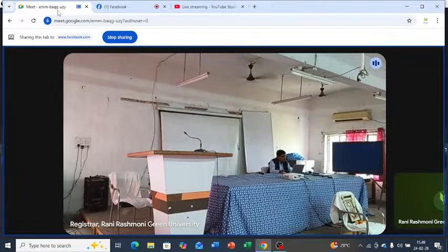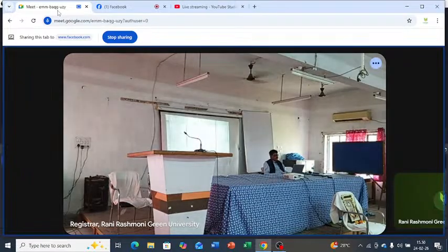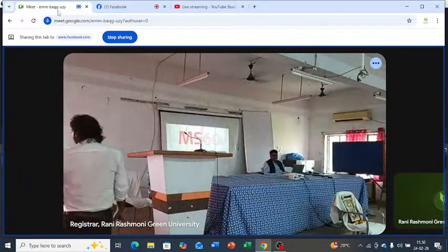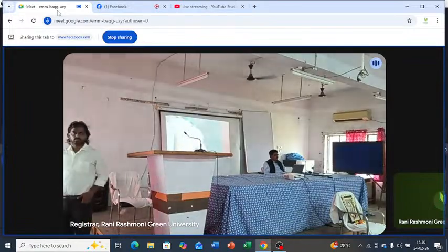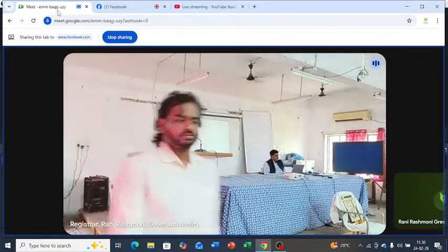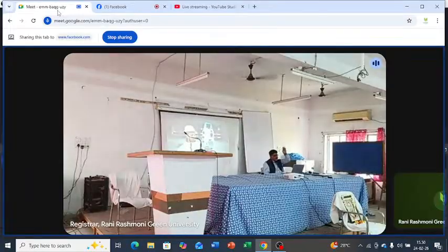So we have got a total station which is the highest model of the total station, called LS60, which has all the functionality of a total station. In addition, it has got a terrestrial laser scanning facility. Now you can see how it moves. It actually scans the area around it.